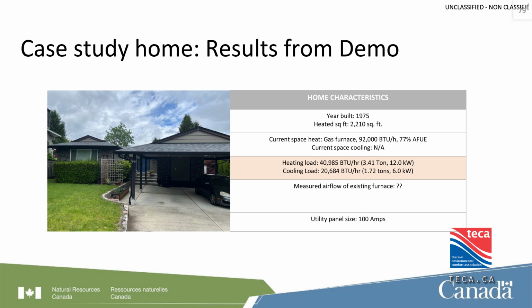We'll create this particular project in VoltaSnap, and here it brings everything in. There's a few modifications that we would have to do. We need to find out what the CSA F280 weather location is, because that could differ from the HOT 2000 weather location. So that's something that we would have to change. In this case, Burnaby. And once we have that set up, we can go to our top menu, and there's an option here. This just shows you how quickly this can be done.